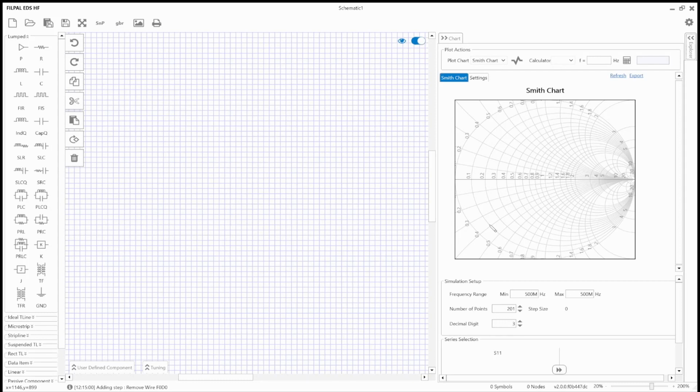Hello everyone. In the previous video, I showed you how the Smith chart, which you can see on the right hand side, is conformally mapped from the familiar rectangular impedance coordinates onto a polar plane. Essentially, the reactive or vertical axis has been bent around in such a way that plus and minus infinity is included within the boundary of the chart.